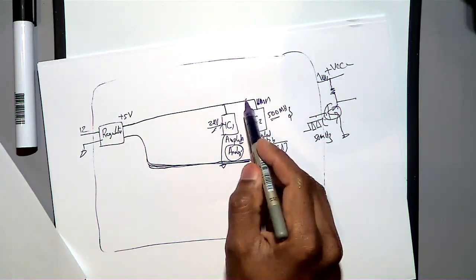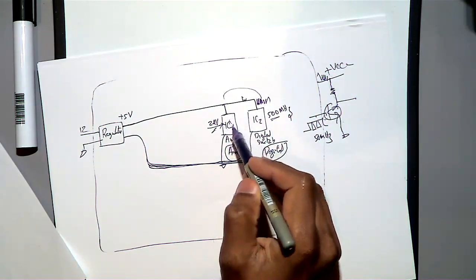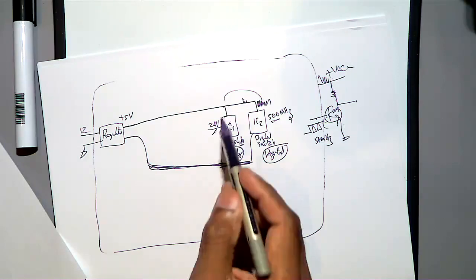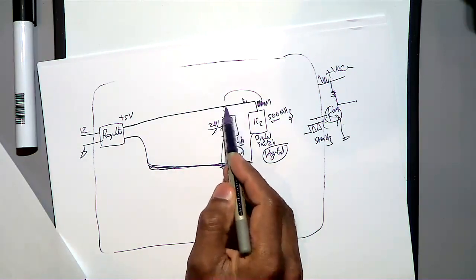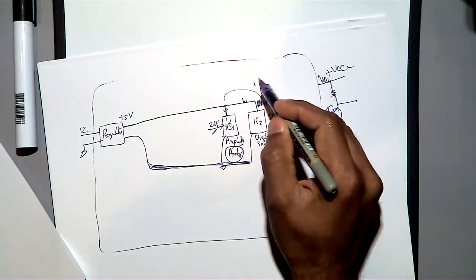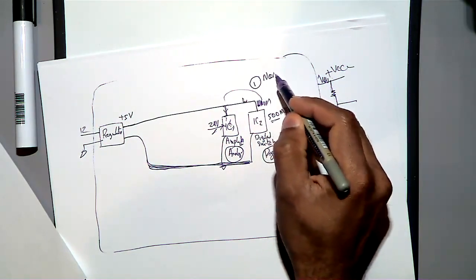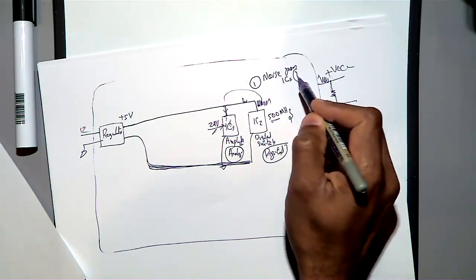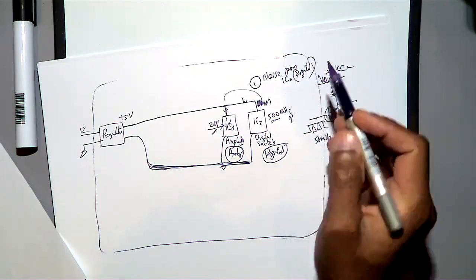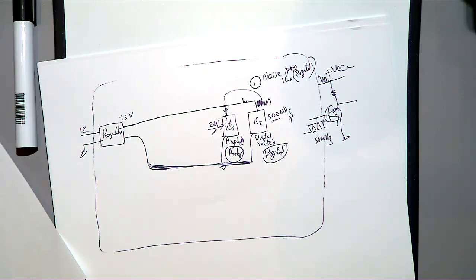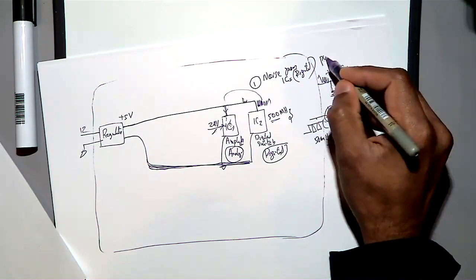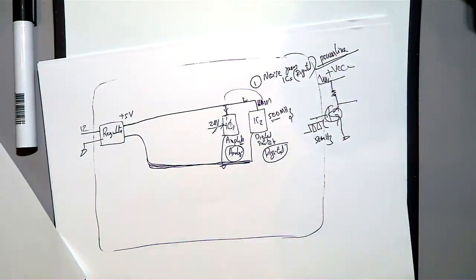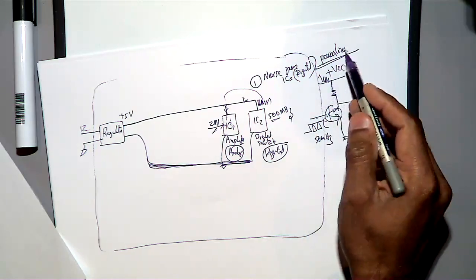That noise will go to the power supply, and then this noise can come to your analog IC. Then your analog IC has a problem. See, this noise is coming here, then it will couple to here. So this is issue number 1. The problem number 1 is noise from ICs, especially digital, on the power line. That's the reason I have written power line here.